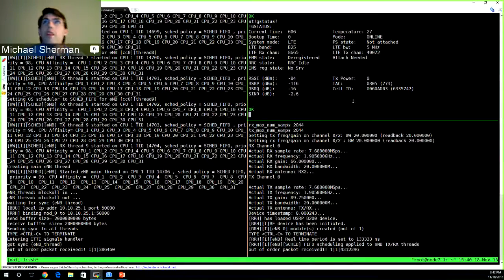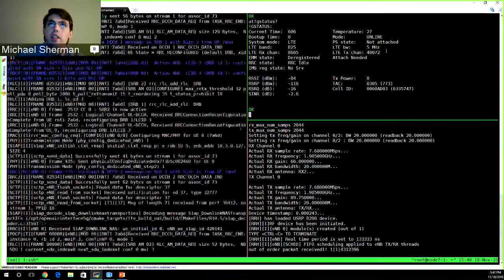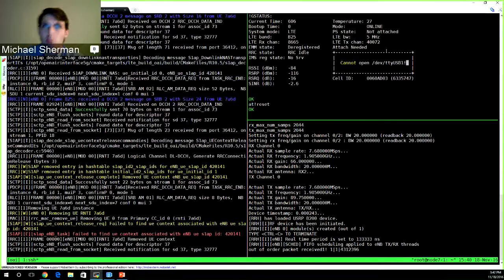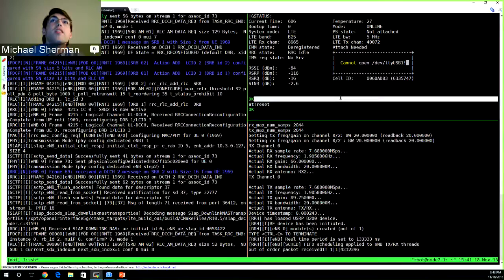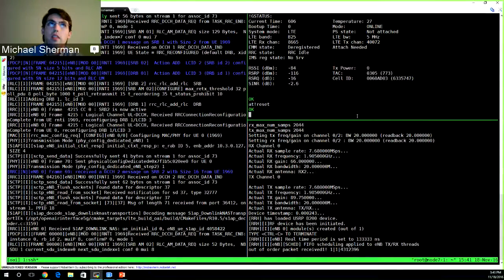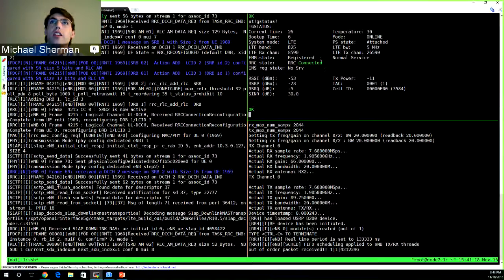And so we told that to run on band 25. We see that's now band 25 and 5 megahertz, which is what we've told it to do, but it's not quite associated yet. So I'm just resetting that USB modem to force it to reassociate. And we should see some messages start popping up as it associates. Yeah, all these blue messages, it should be coming up now. It was losing the context of the client and then setting it back up again. Okay.